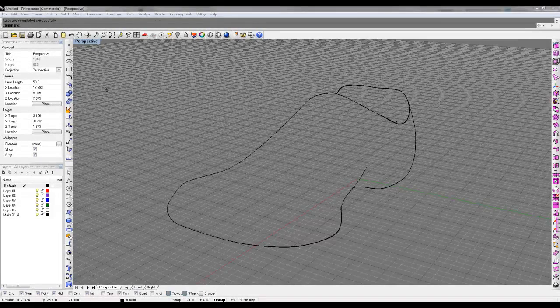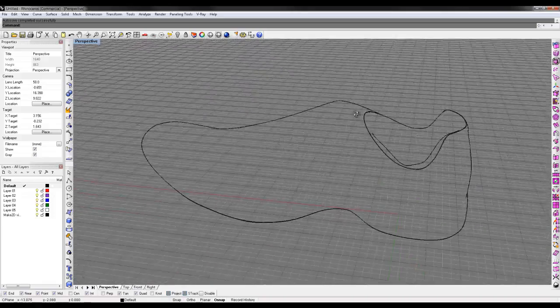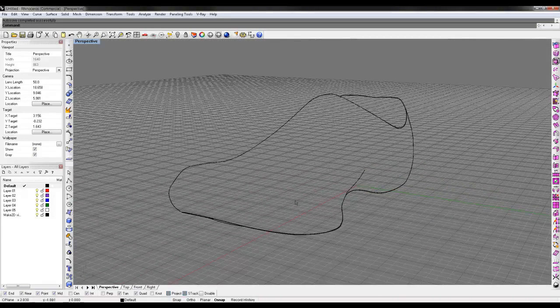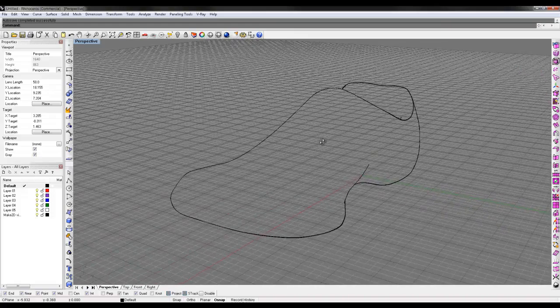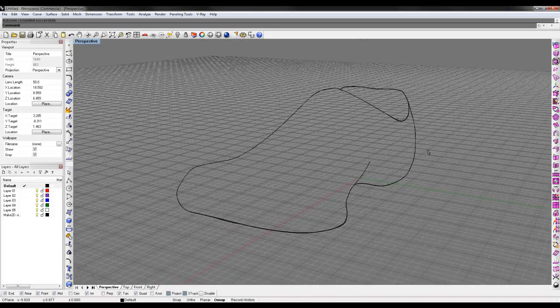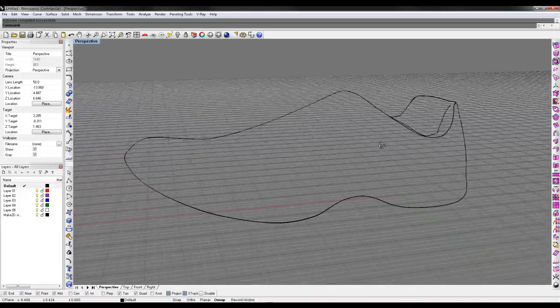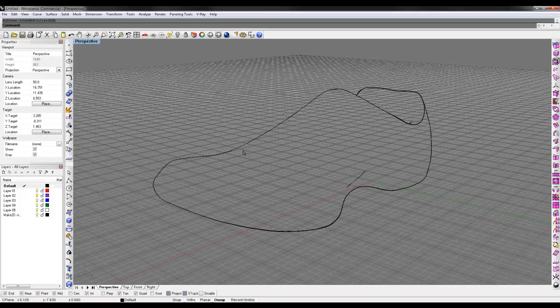A couple of weeks ago I talked about the technical drawing mode, and what this does is it creates a sort of silhouette of whatever your object is, with just an outer perimeter and the edges highlighted, so there's a graphic look to it. And I had mentioned that I wanted to go over in the next couple of weeks the Make2D command specific to Rhino, but a lot of other software packages can do this, more on the engineering and drafting side, like AutoCAD and SolidWorks. The reason it's so cool is because you can get a little bit more control with your curve.